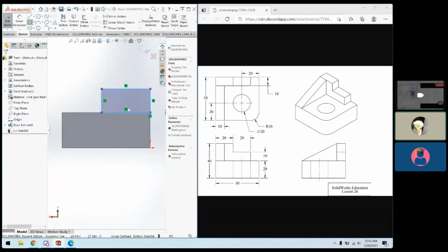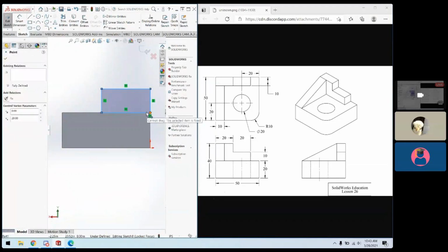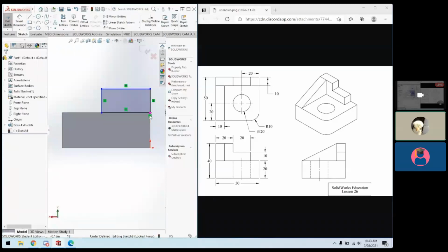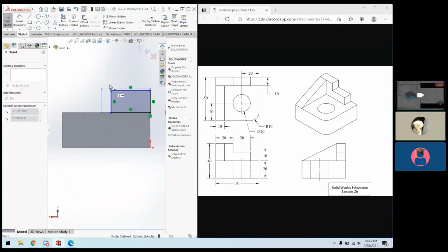So if I finish the box, this line basically means that you cannot move this corner. It's always going to be intersecting with the point or the corner of the model, whereas this point, you can move. And another thing you can tell is that these two lines are black, meaning that they're defined on this location point. So yeah, and then we can do the other side and the other corner at this, sorry, the step rectangle at the same time.